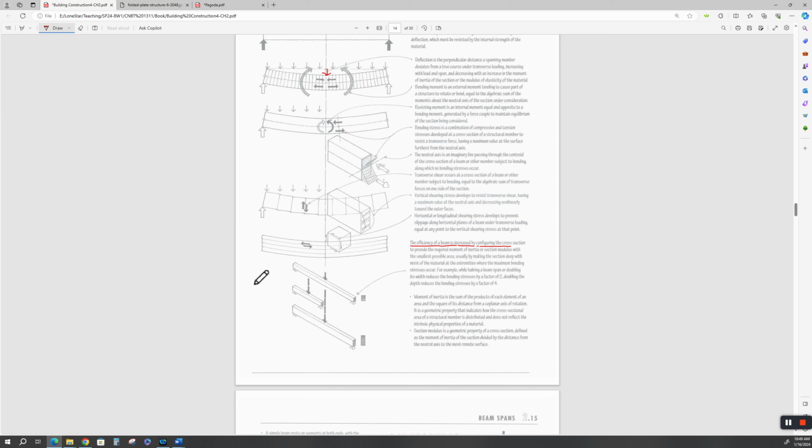That's why if you just take, let's just say a 2x6, you're going to use it as a beam, then the longer the span, the less it can carry. And the longer the span, the more it wants to roll over, it wants to rotate, lay down. So, what do you do in wood construction? Maybe you take a couple of 2x4s and you laminate them between a giant sheet of plywood.